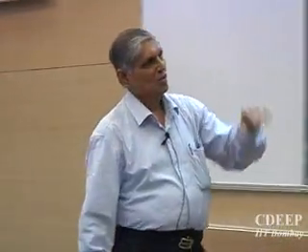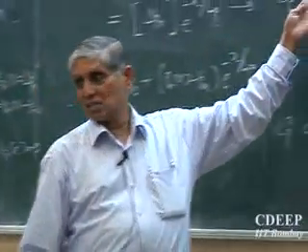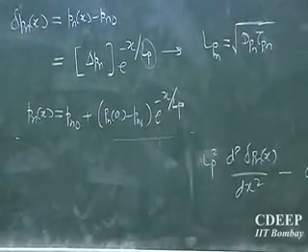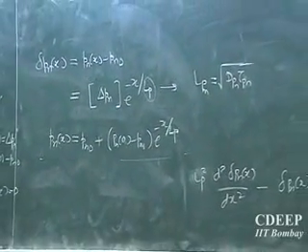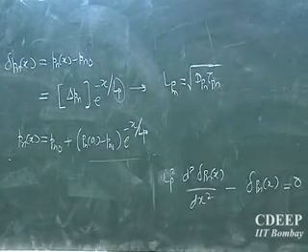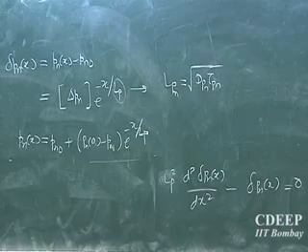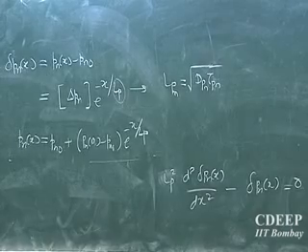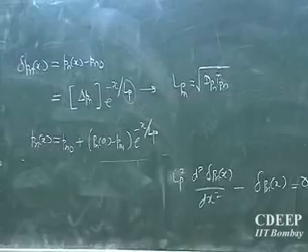So that issue, that both diffusion as well as recombination is taken care of by one single parameter which we call the diffusion length. Another thing you should keep in mind: I have not solved so much for holes in p-type. Why? Because their concentration is already high, 10 to the power 15, 16, and this delta will be smaller than that. So the additional term which you are getting in excess carrier is small enough that p is approximately p0, and therefore it's not that it doesn't decay, it still has to decay, but that is not so very